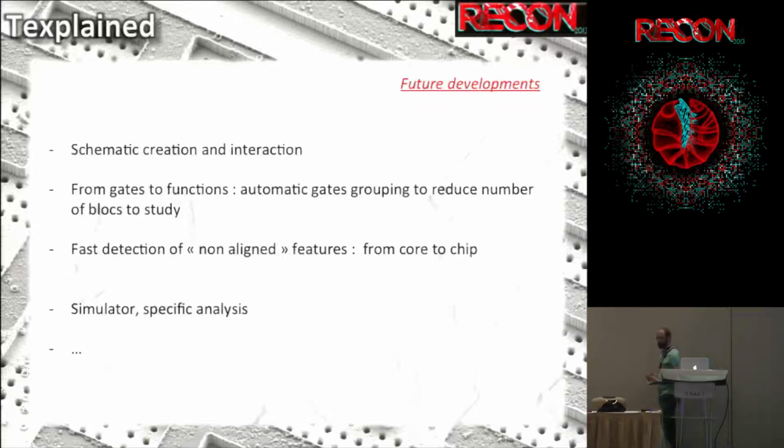For this, there is something which is very easy, because the software is extracting gates. So it says, for example, I found this type of gates 200 times on the chip. All right. But now you can just look at the link between the gates, and you will find that this gate is always linked to this one 5 times on the chip. So they are linked 5 times. It's not something that is random. It must be a function.